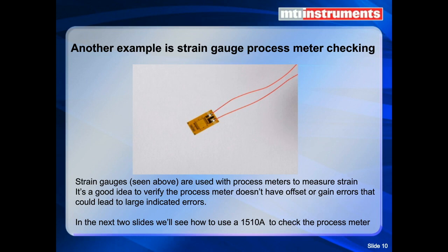This little guy above, you see here, he's just 2 wires, but typically you find 2 of these things set up in parallel. One is to cancel the effect of the other in terms of voltage and aging. And these things are quite often connected as like a quarter bridge or a full bridge. What our signal generator can do is to simulate the output of this strain gauge.